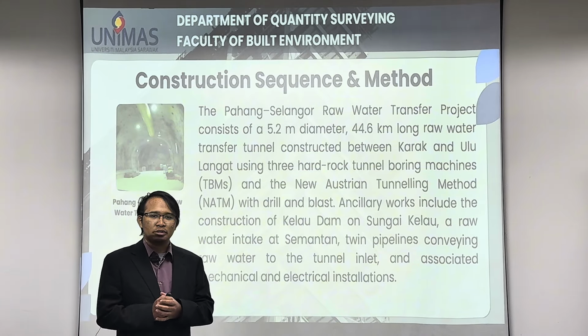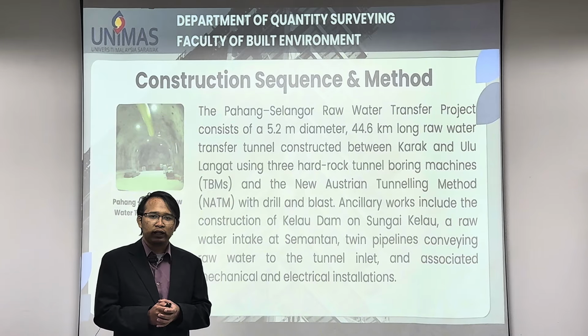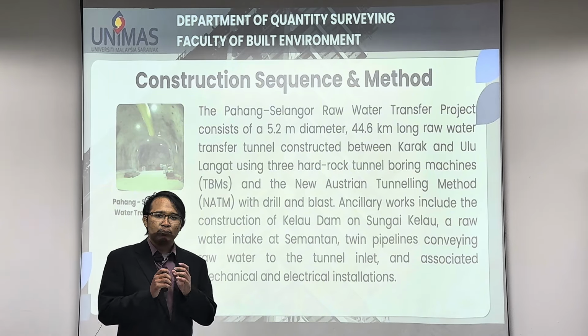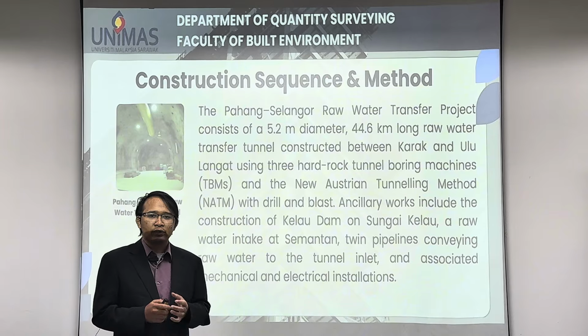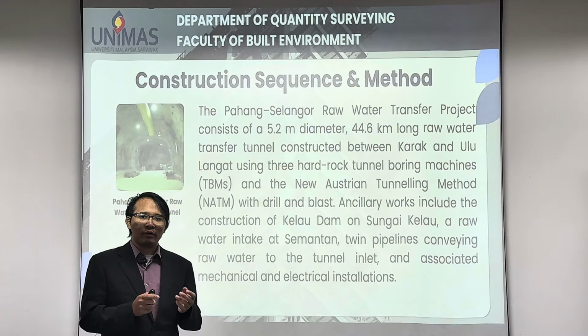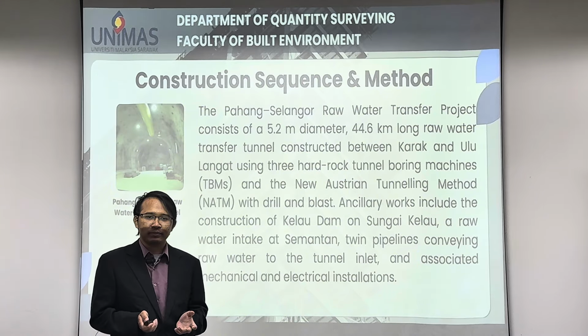The second method is the New Austrian Tunneling Method, or NATM. This method is used in difficult ground conditions such as fractured rock. NATM relies on ground support: rock bolts, shotcrete, and steel ribs.